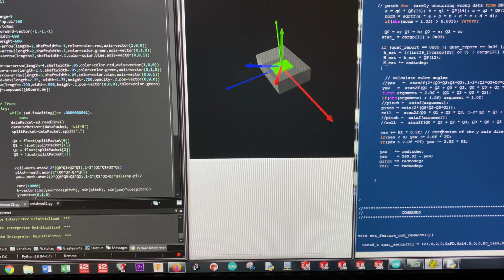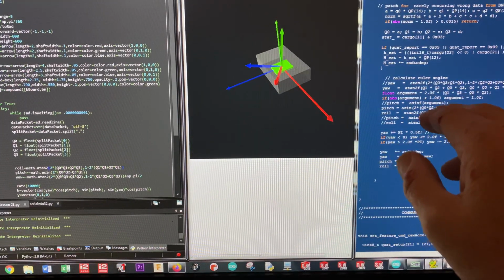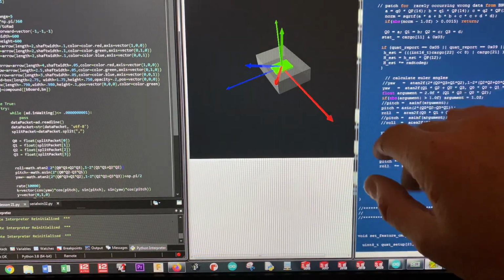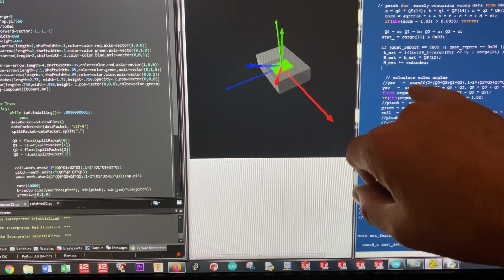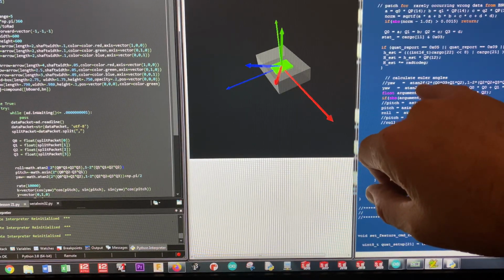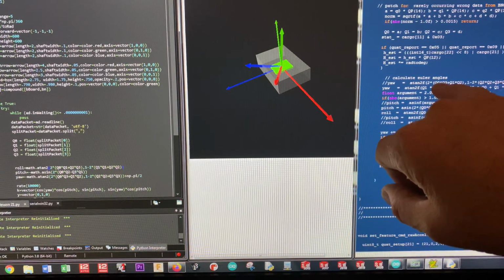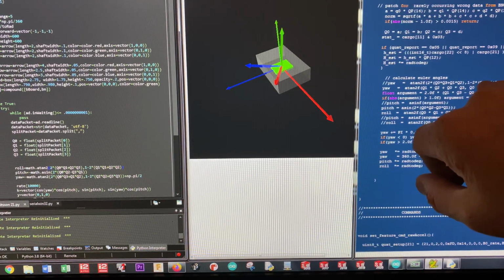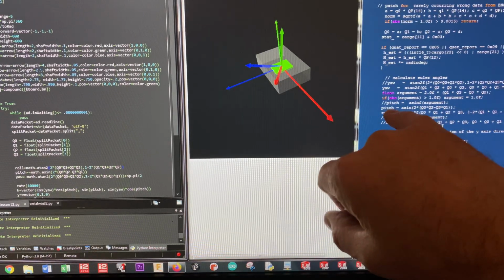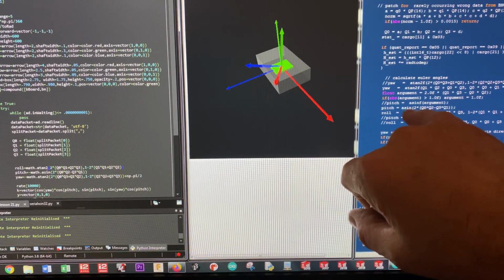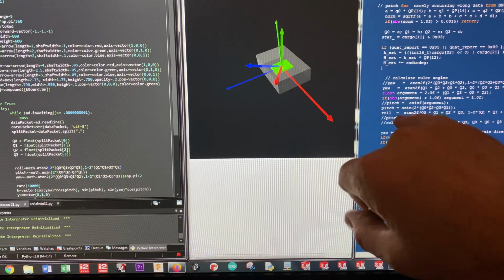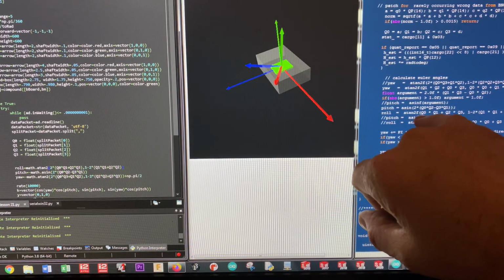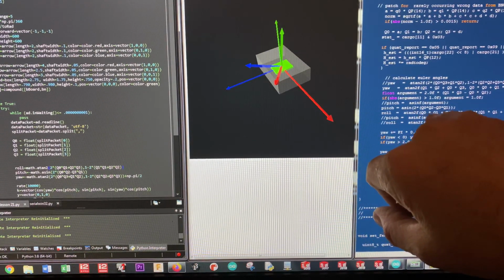In the code over here, I have it all being run on the microcontroller to spit out the Euler angles, and it's just simple math equations. If you take the quaternions, yaw is the arctangent2 of these quaternions multiplied against each other, added together using Hamilton's math, and pitch is the arcsine of the quats, and then roll is the arctangent2 of the quaternions.